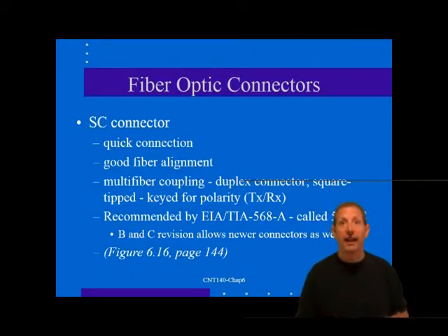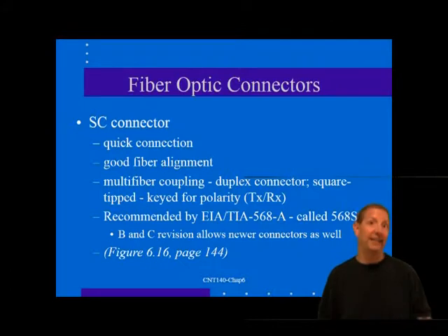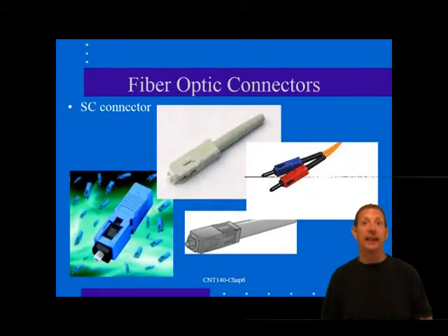The square design and push-pull coupling mechanism make the connector usable in high-density applications. The SC connector may be coupled in duplex sets with a coupling receptacle or duplex clip. In a keyed duplex set, the SC connector easily implements a form of polarity matching with coupling adapters in fiber optic outlets or patch panels.